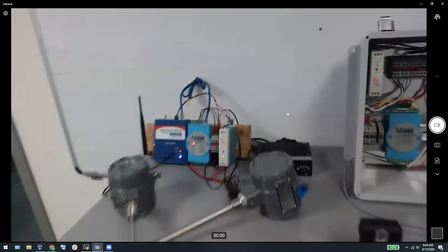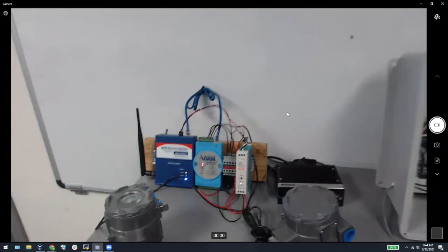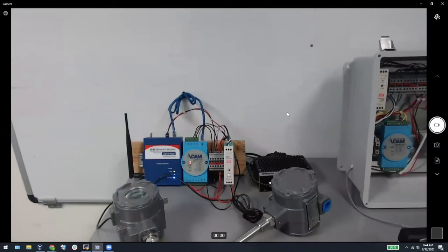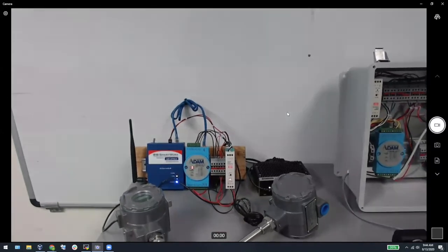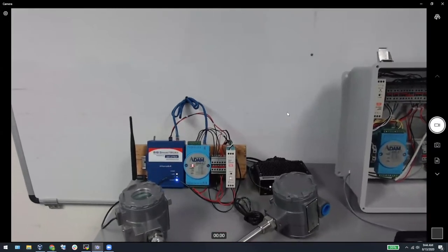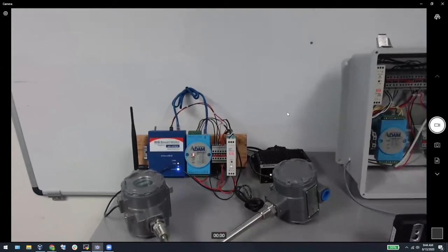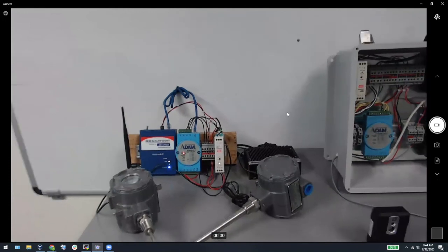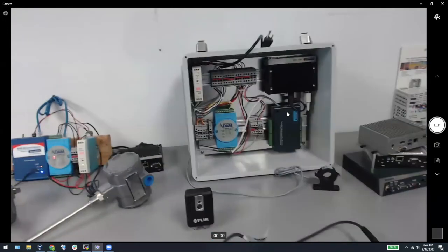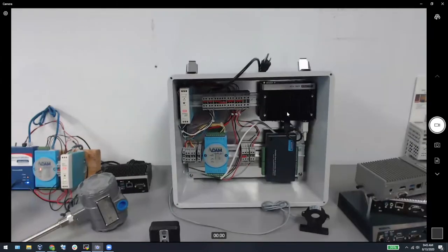On the left-hand side here, we have different data acquisition modules that we're using to collect data. This is a typical industrial setup where you would have a data acquisition module collecting 4 to 20 milliamp current loop and analog device information, bringing that into a data acquisition module, and then using a protocol such as Modbus to collect that information into Fledge using our Modbus plugin. We have other industrial plugins like OPC-UA, for example. Nexcom has contributed the J1939 protocol as well to the Fledge repositories.